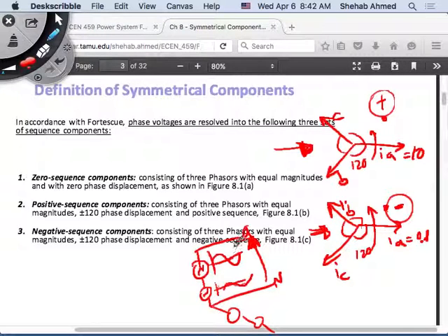So what do you think will happen if I apply both, but one is much more significant than the other? Torque components in the motor are due to the flux components in the air gap. Flux components are due to the currents and voltages that you apply on the terminals of the motor. So you will have components of flux and current due to this source, and components due to this source. It's superposition.